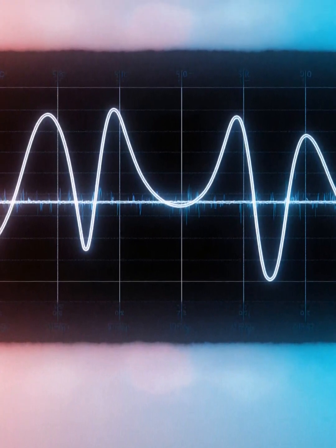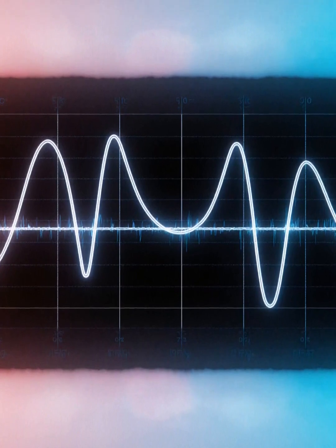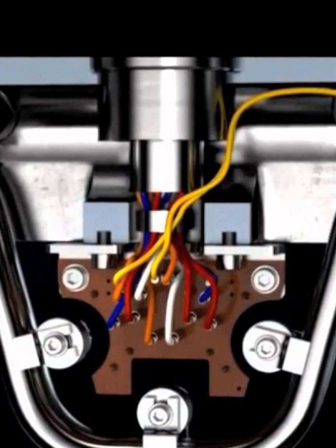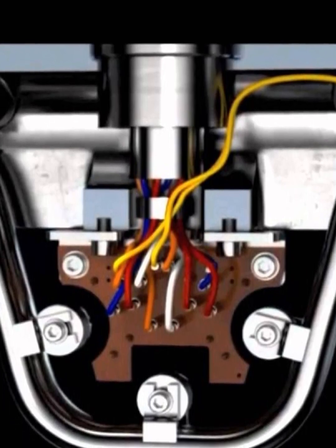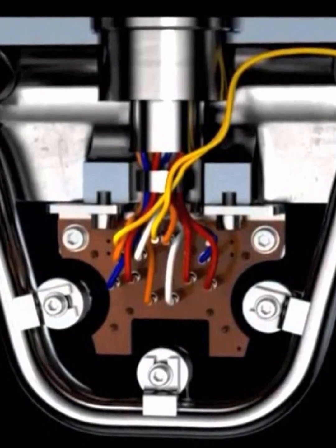As the tubes oscillate, the voltage generated from each pickoff creates a sine wave. This indicates the motion of one tube relative to the other. The time delay between the two sine waves is called delta t, which is directly proportional to the mass flow